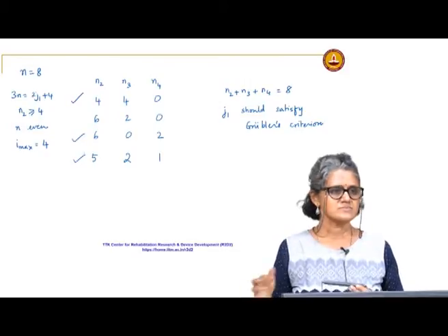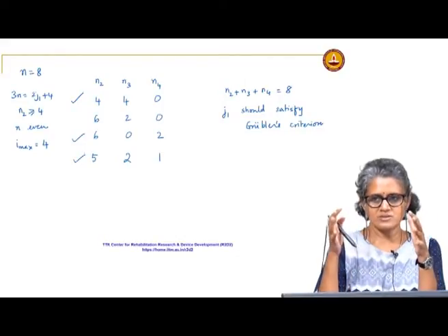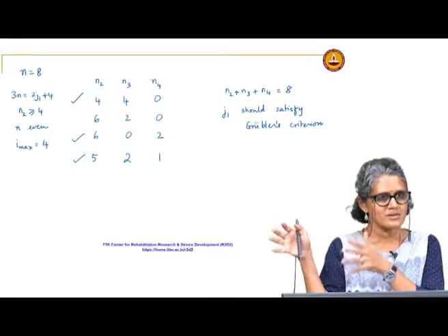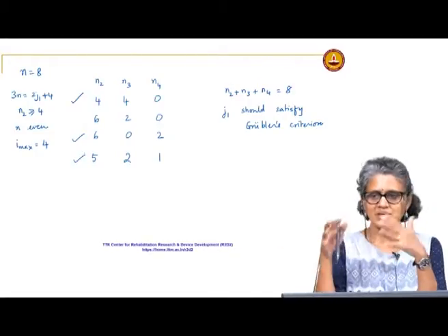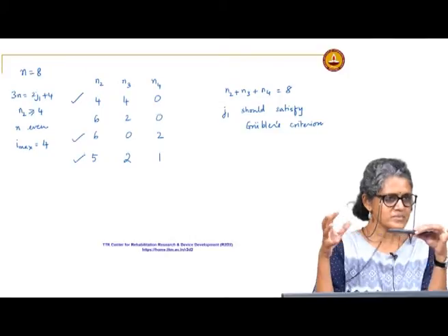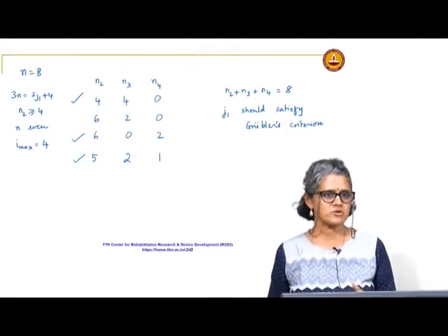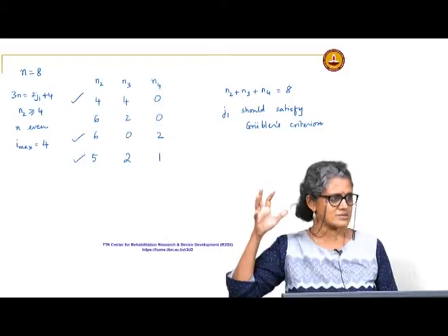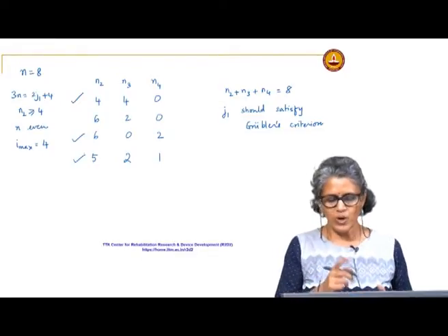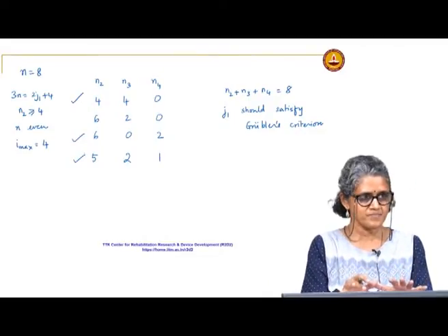In many cases you are actually doing it as building blocks. You take a 4 bar, then maybe you add 2 more links to drive it, or add another parallelogram mechanism to it to make an 8 bar, etc. So, the mechanisms that you will encounter in real life can typically be broken down into smaller units. You will see that even though overall if you count the number of links, it will be an 8. It is very rarely that you say, okay, I want to design an 8 bar, and you go about doing it this way. Okay. Now, once you get this, so this is for everything having simple hinge joints, okay.